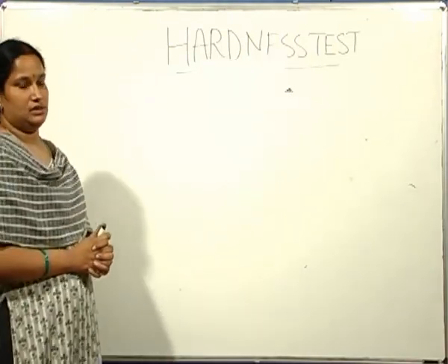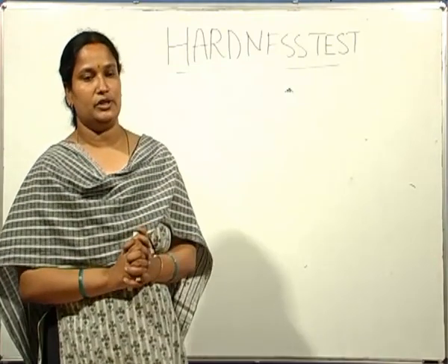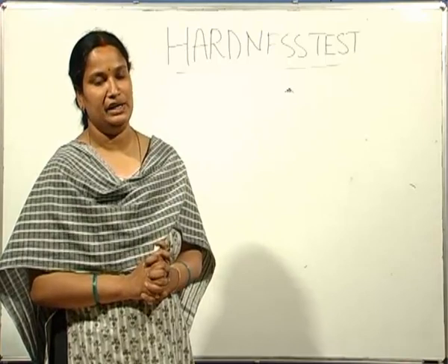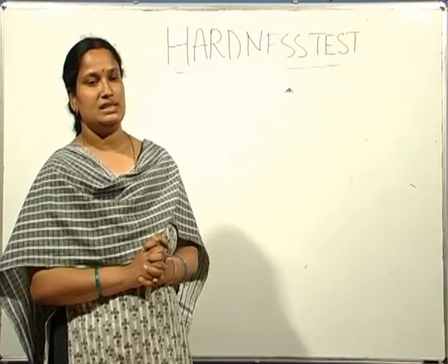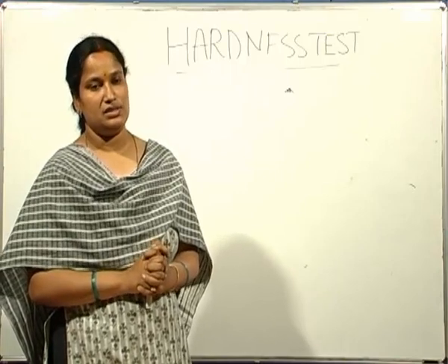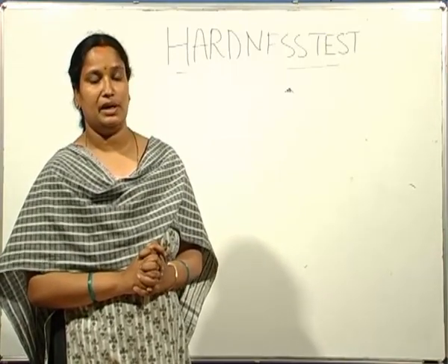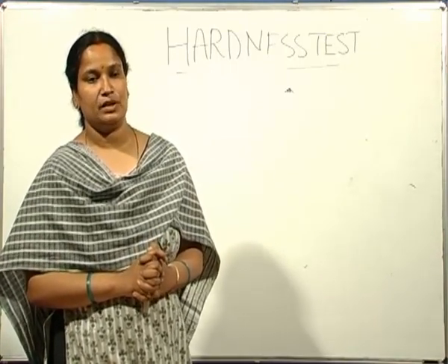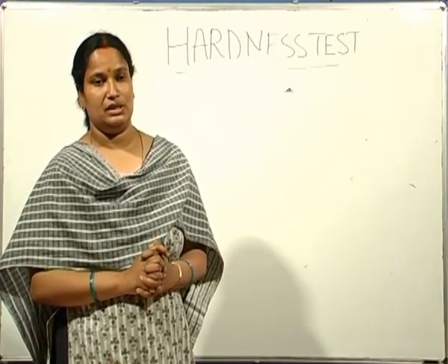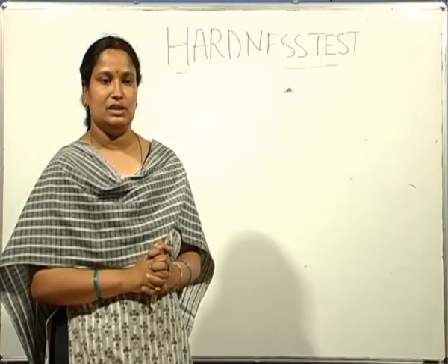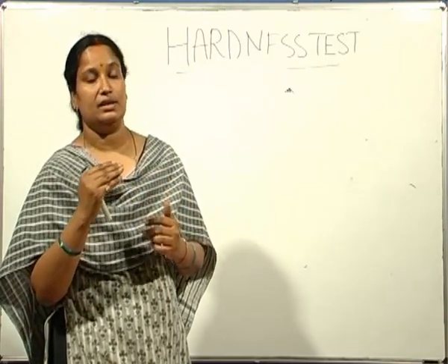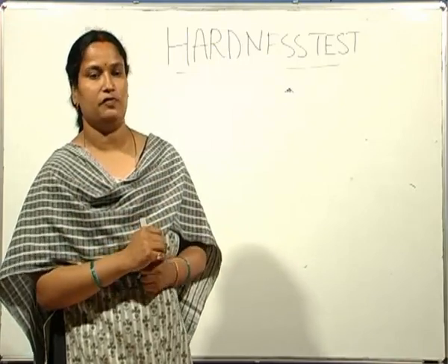It is found that for the case of cold worked metals, Meyer hardness is independent of load, whereas the Brinell hardness is found to be constant at low loads, but as the load increases, the hardness value decreases, which shows incorrectly that as the load is increased, the material undergoes softening.